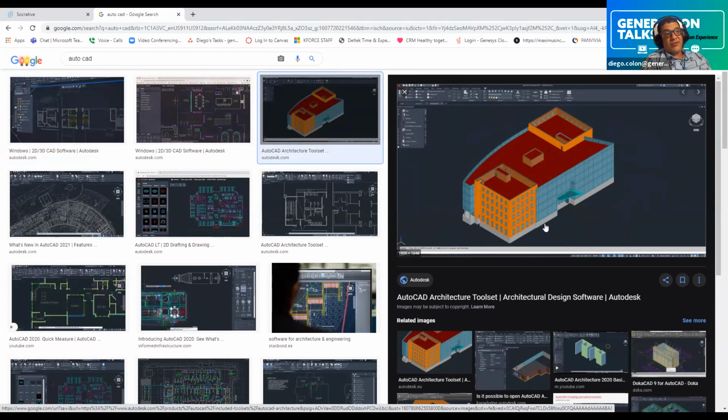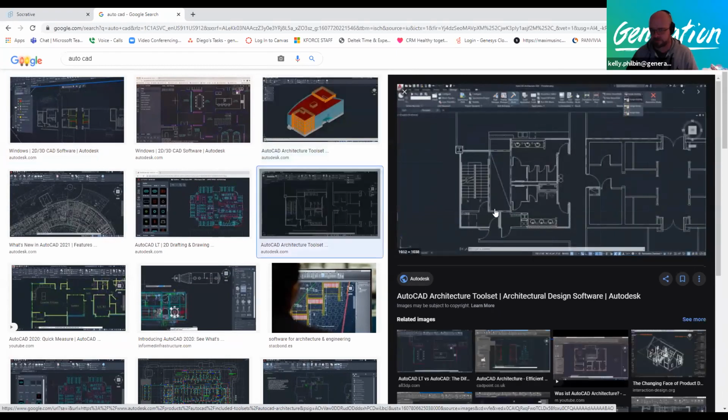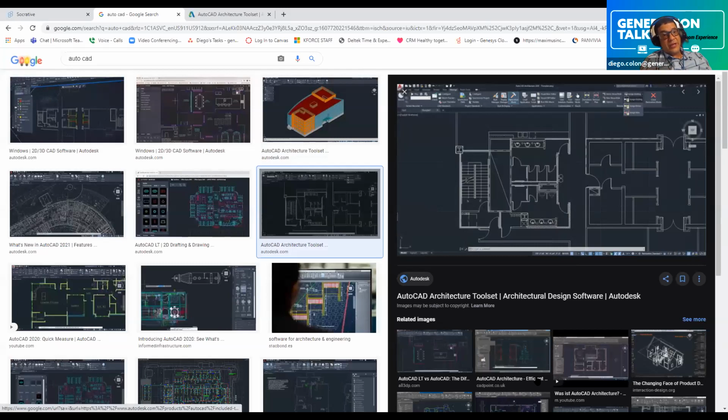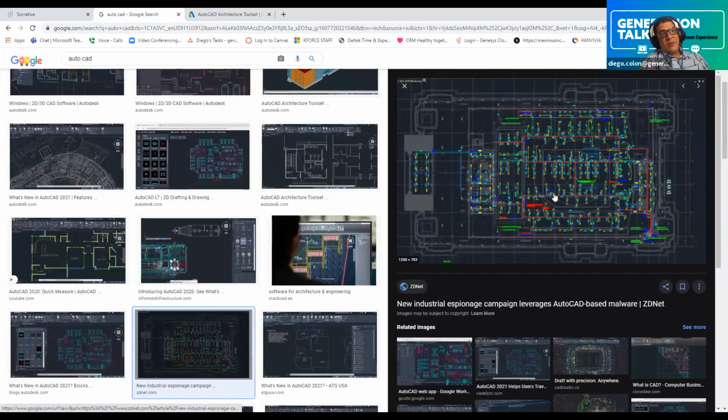So every floor, I can zoom into this thing and check every single floor, how it's built. There go the doors. I'm not sure if anybody's used to reading any of this. That's my stairs. Here's my sinks, my door to come into the main lobby. If you get used to this, you should be able to read this. I am also able to read the actual network drops and everything here. They're going to give you the drawing of the floor with the drops, and you've got to be able to decipher what's what.